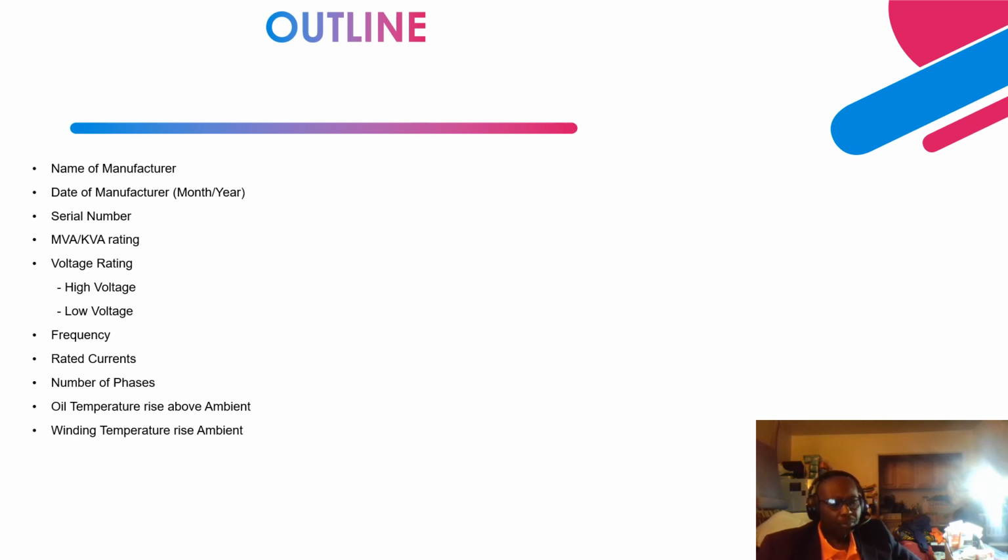Basically, in the past, or many decades ago, right from the 40s, 50s, 60s, transformers had an oil temperature rise above ambient of 55 degrees Celsius, based on the typical insulation materials used in those days. But nowadays, about a decade ago, most transformers that are designed have 65 degrees Celsius.